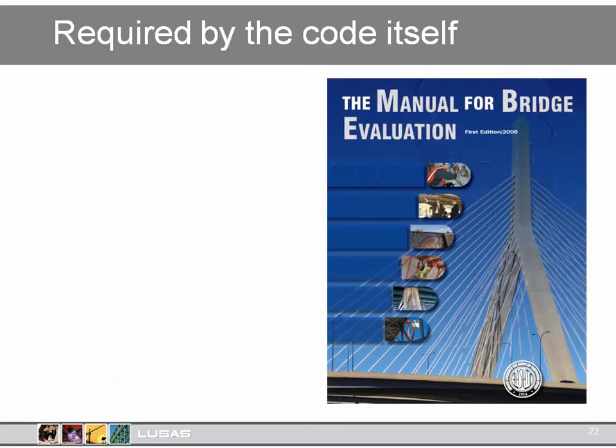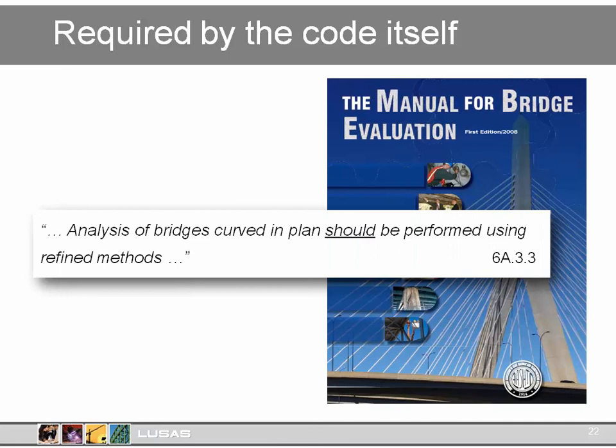AASHTO comes close to requiring finite element for curved girders. The manual for bridge evaluation goes a bit further, saying analysis of bridges curved in plan should be performed using refined methods. Several state DOTs are making this a requirement in curved or skewed structures.